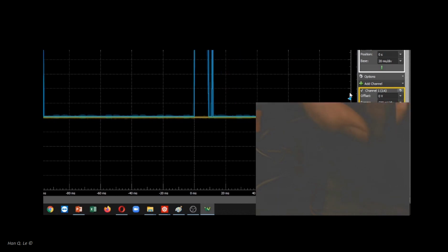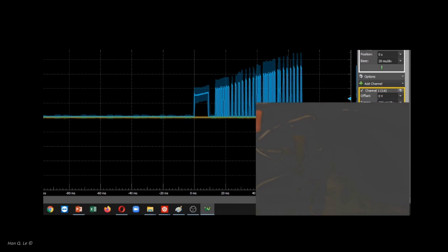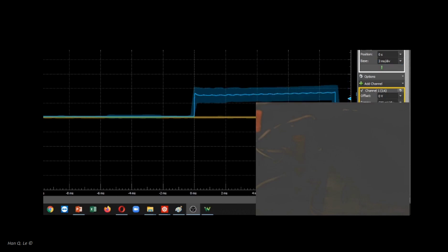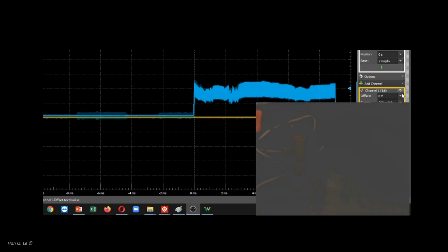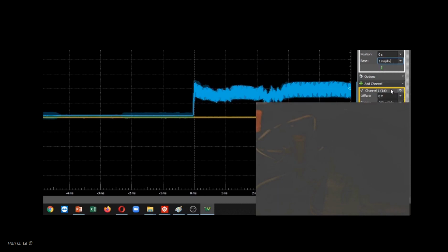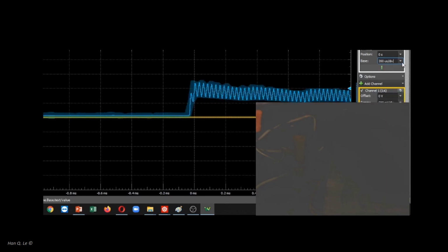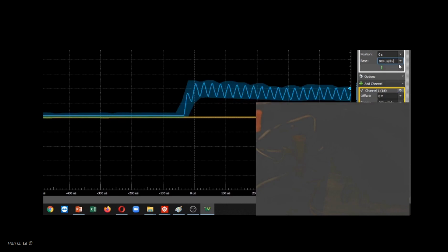Once a signal is captured, use the scope horizontal, that is time scale, to observe the fine structure of the signal. The signal consists of several bursts of light pulses of different lengths. As the time scale becomes finer, such as 1 millisecond per division, high-frequency modulation can be seen within each burst pulse. This is called carrier modulation. The purpose, like a special pitch whistle a coach might use to catch the attention of the coach's team players, is that this modulation catches the attention of the appliance, knowing that this message with this unique pitch is from the remote control and not the room light or a flashlight, for example.